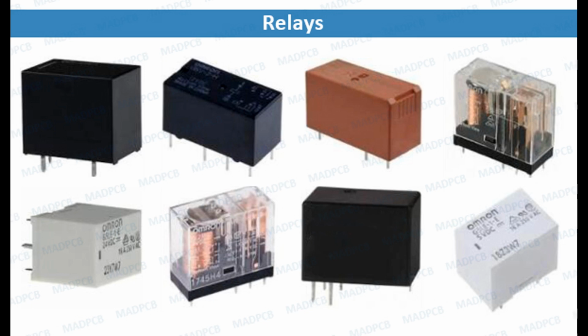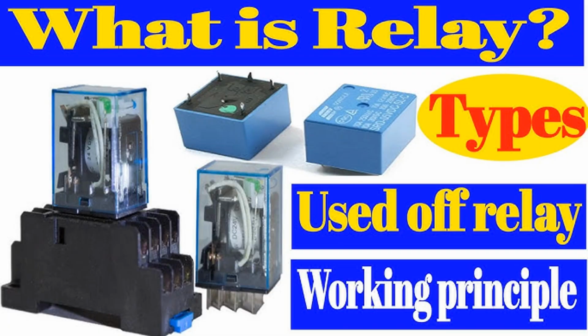Advantages. Power savings. Only consumes power during the switching operation, making it highly energy efficient. Maintains state after power loss. Retains its last state, which is valuable for safety-critical and memory-sensitive applications. No continuous coil current. Reduces heat generation and wear on components, increasing the relay's lifespan.